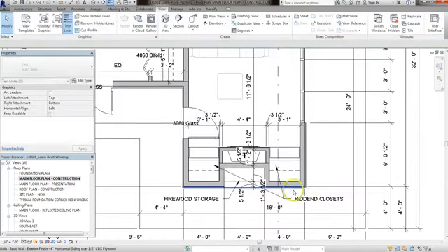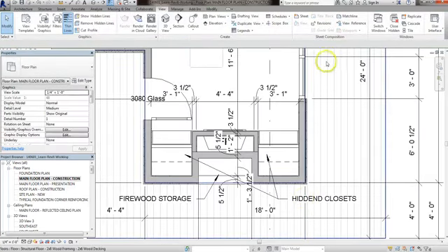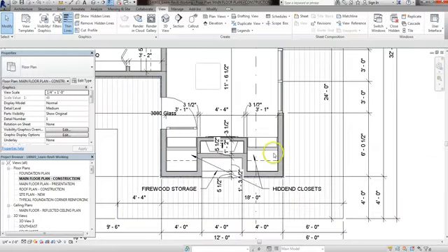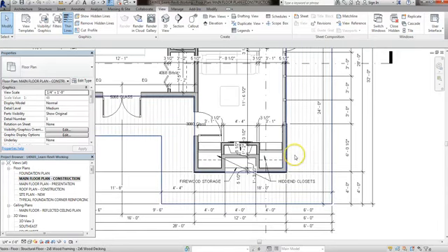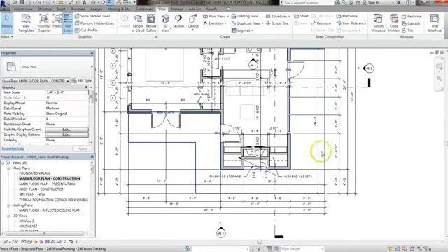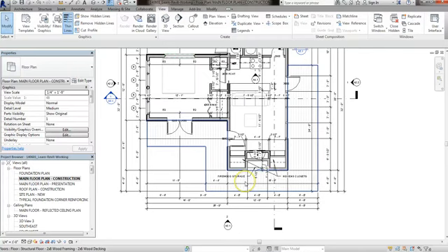Move right there. So you'll notice on sections and on plans that a lot of architects use a segment, a line that kind of bends at an angle. And the reason is, if you only use straight lines and called out straight stuff, it would get confused with the architecture. It'd get confused, like, is that line a poche for the deck here? Is that line part of the window or part of the dimension? So when you're doing any text, try to do the 2 segment lines because it makes it clearer, just intuitively and professionally.